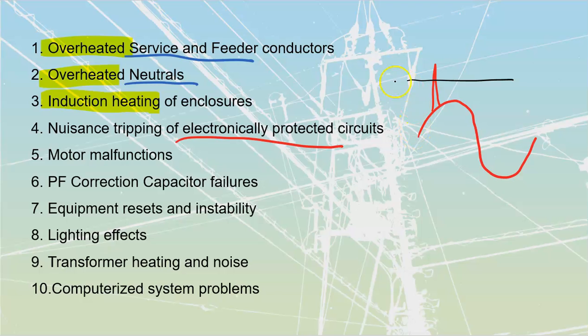They don't care how long it exists over top of that threshold, and they're fast enough that they can catch it. A regular fuse or circuit breaker does not have enough time to catch a fast-moving spike, but electronics are able to read down into the nanoseconds. They just see that it crosses that line, and as soon as it crosses the line, they don't know for sure how long it's going to stay up there. It could be a legitimate, huge current spike that's going to stay up there for a long time, so they just react as soon as it crosses over that.